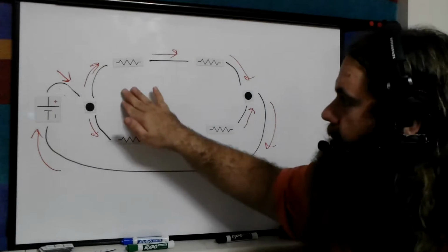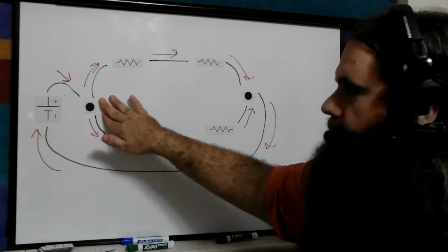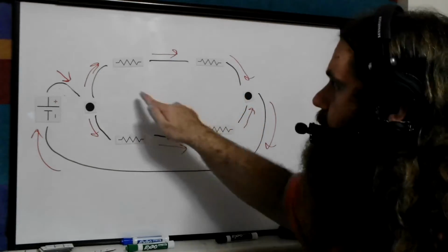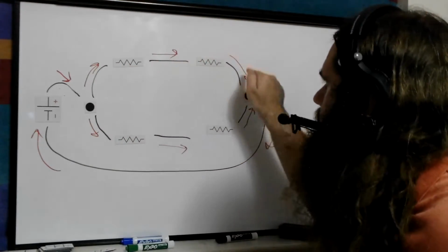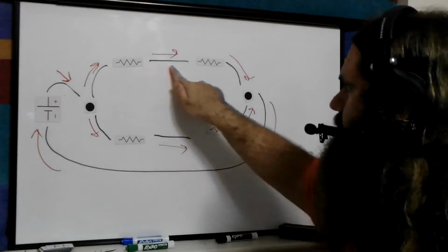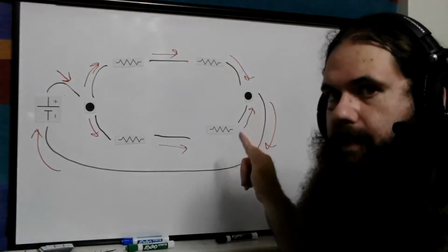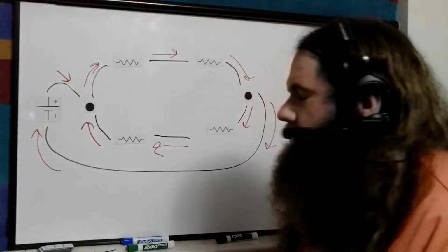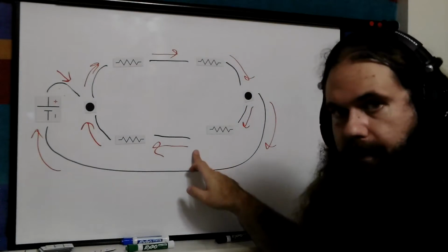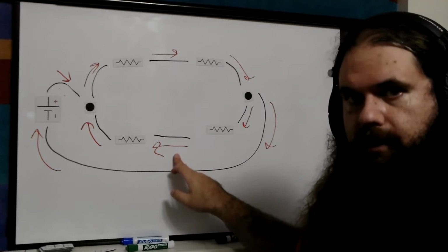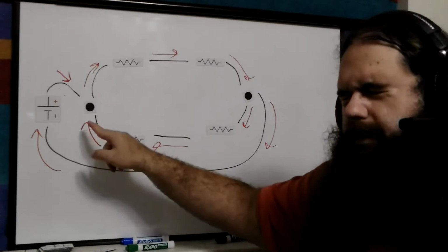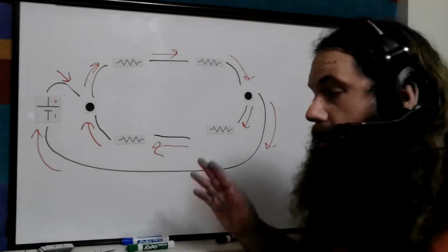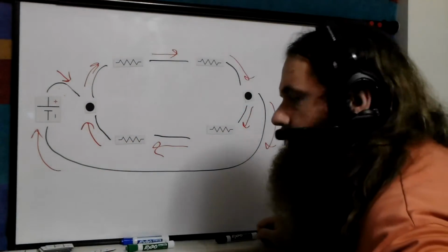But remember, when you're not at a junction, the current has to stay the same value, same direction. So you couldn't have here, then here, then here. Starting from a junction to a junction, the arrows must keep pointing the same way. I could flip this if I wanted. That's obviously wrong, and if I do my math, whatever I calculate for this current will be negative. But they're consistent. From this junction to this junction, they're facing the same way. That's all you need. So why does this work?